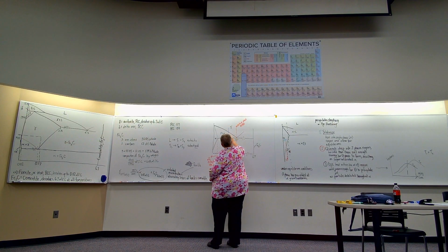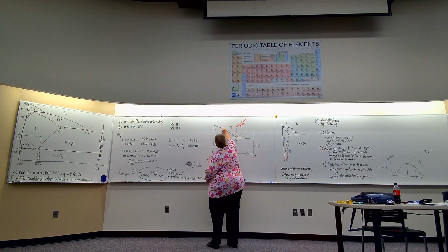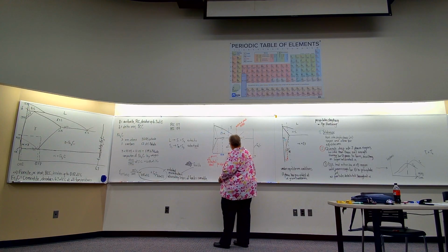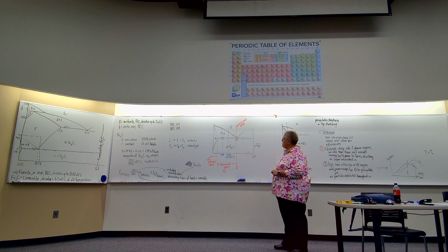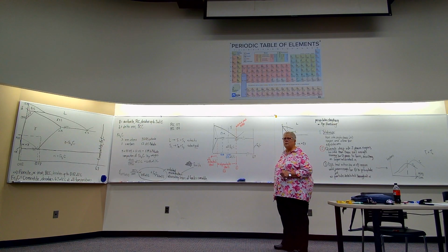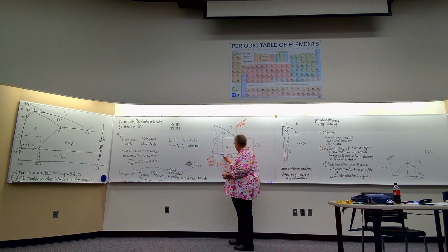There's one steel that will be here, and there's one steel that will be here. 0.18, sometimes we'll just call it 0.2, and 0.4, or sometimes 0.45, depending on the steel. So really, those are the only compositions that we'll look at: eutectoid composition, a 1018 or thereabouts, a 1040 or 45. You'll be looking at 1018 steel from the lab.